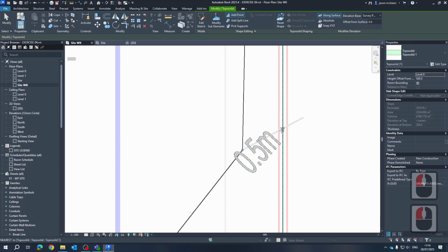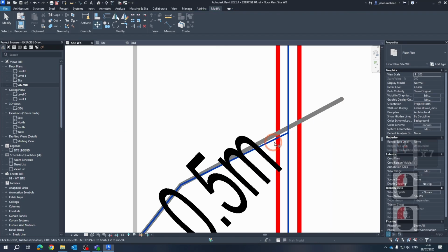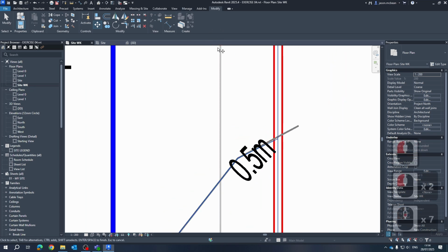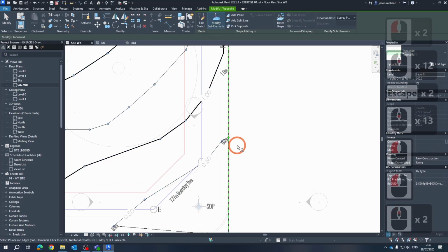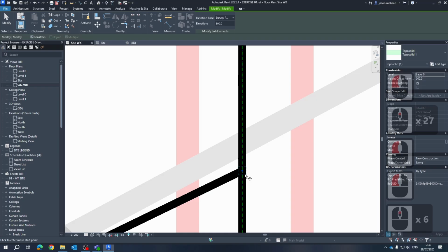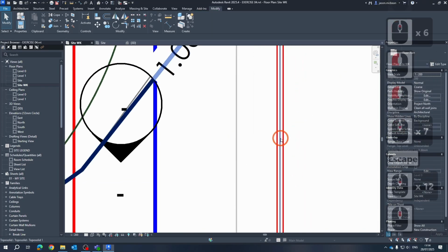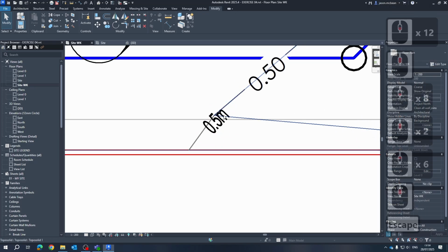So if I snap, you have to snap on the boundary, and then you've got to move the boundary. I've noticed sometimes, the older version of Revit was pretty good in this respect, that it was very easy to manipulate your contours. This is a new tool that they've introduced, and in my opinion it's still a little buggy. So I'm just going to move this where it snaps roughly over there. Okay, so that's my 0.5 contour, and I can still see there's a little bug over here.